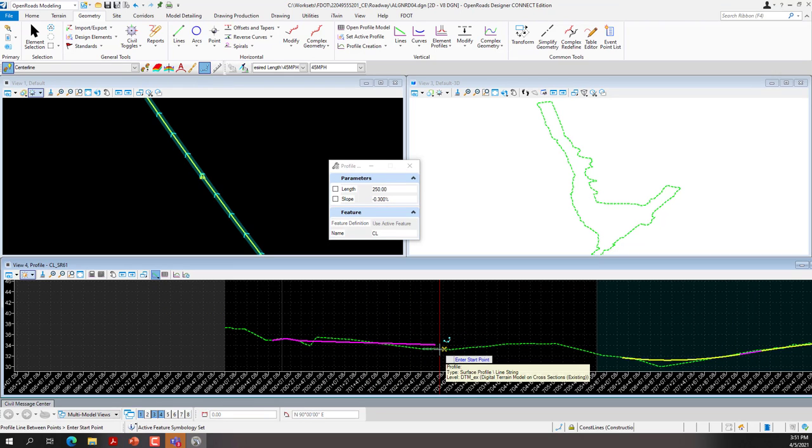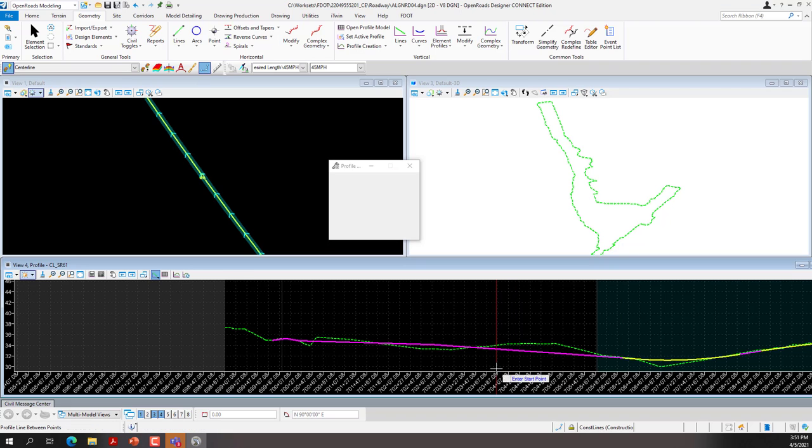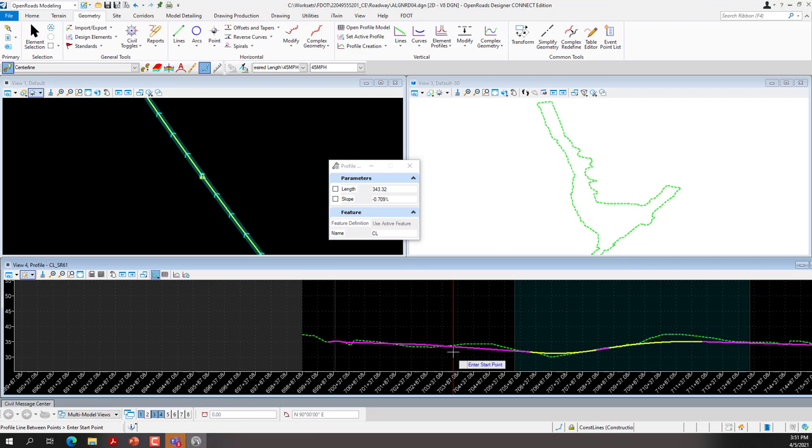And then the ending point that we want to put in, we want to snap to the end and then just snap to that. So that's designing over US 98 and then using a 250 foot line with a 3%, and then we'll connect our PI to our curve.